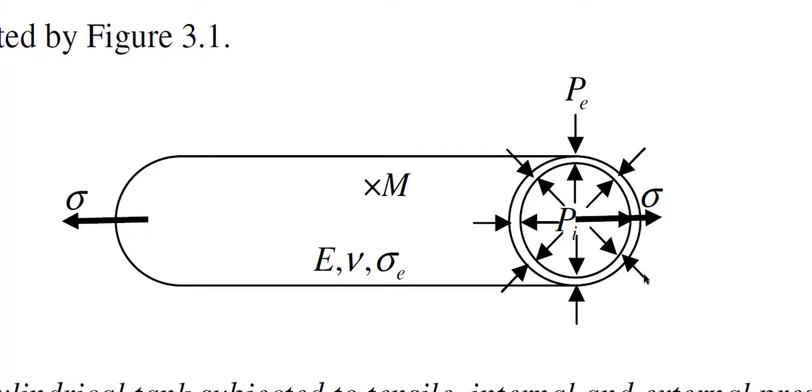Now for the longitudinal displacement uz, it's to note that the points having the same longitudinal coordinate z will have the same longitudinal displacement uz, even if they have different radial coordinates and different circumferential coordinates. So the longitudinal displacement uz will depend only on z.